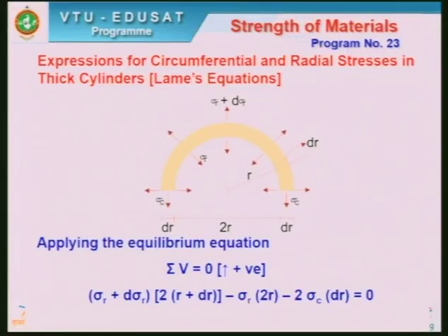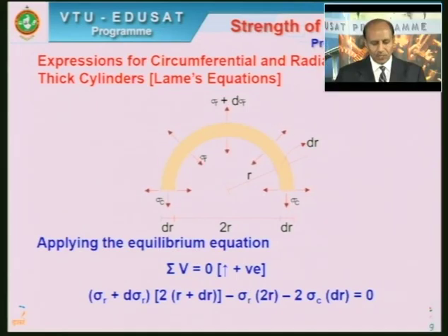When you look at this diagram, we have represented the radial stress as tensile. So how do we apply the equilibrium equation? It's quite simple. If you recollect the bursting force we defined in presentation 1: the bursting force due to any pressure acting in the radial direction is calculated as the product of the pressure and the projected area of the curved surface on a horizontal plane.